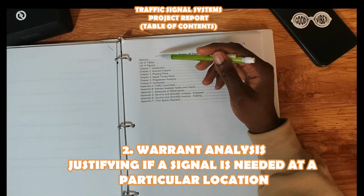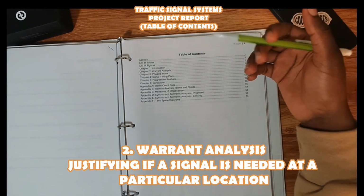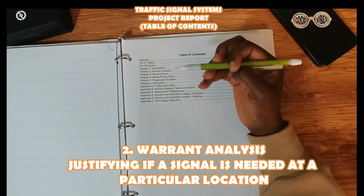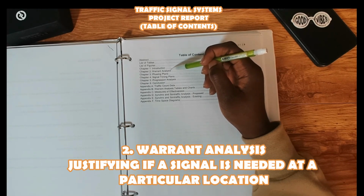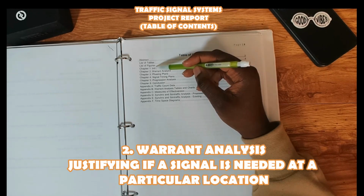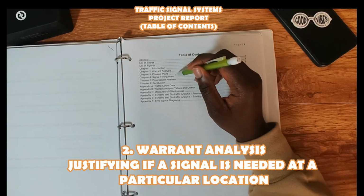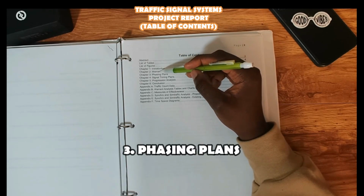For the next chapter, we have a warrant analysis. Whenever you're putting in a signal or you're trying to retime a signal, you have to justify if that signal is actually needed at that location, which is a warrant analysis. I believe there's 7 of them that you have to run through. But yeah, we have to justify that a signal is needed at this location. Once it's justified, we can go ahead to create phasing plans.